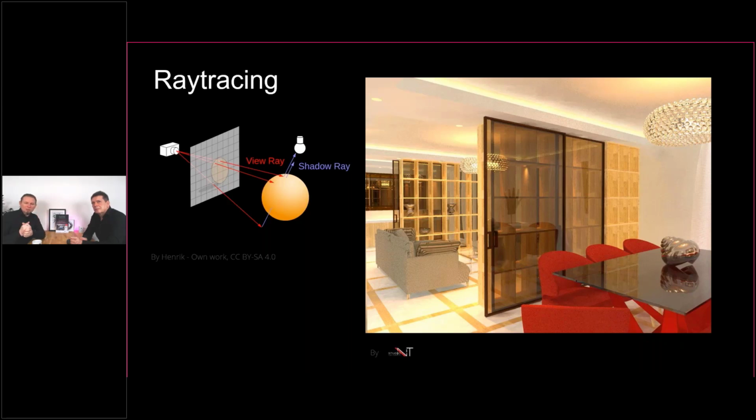What do I need from a lighting calculation? If it's values for meeting a standard, then go with the radiosity standard out-of-the-box calculation in RELUX. If you want a calculation of reflections or transmissions through glass or with a mirror or metal or whatever, plus maybe a nice looking picture, then go for ray tracing.